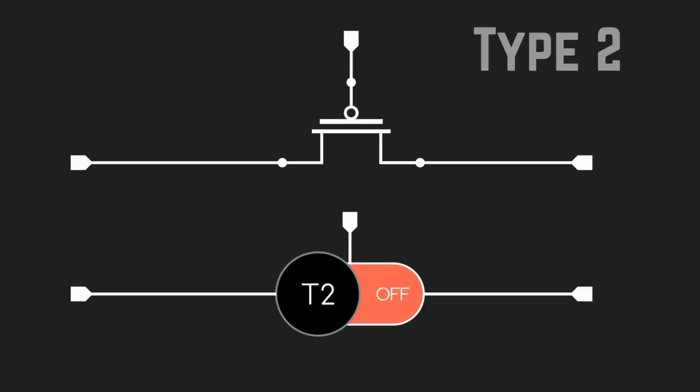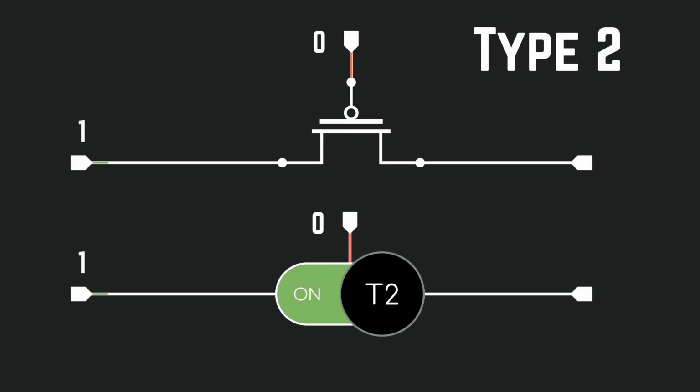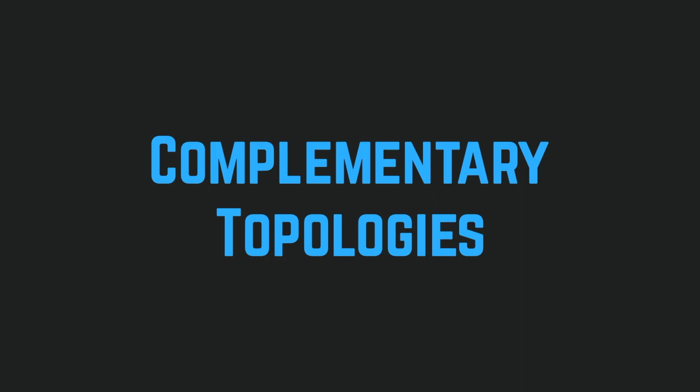The second type of transistor turns on when a logic 0 is applied to the transistor, and is good at passing a logic 1, which again can be visualized by losing little to no water. However, if a logic 0 is applied, then we end up with a voltage that does not equal the logic 1 or logic 0 case. To ensure that we always end up with a logic 0 or logic 1 at the output of our circuit, we use both types of transistors, or switches, in what is referred to as a complementary fashion.